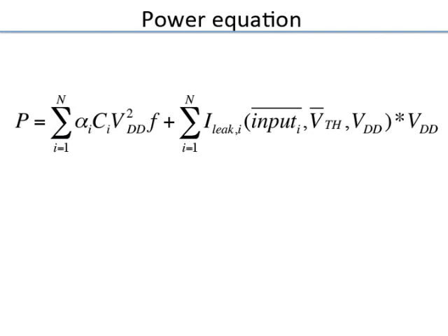If you recall, there is the DIBL effect. The off stack in the CMOS sees a complete VDD voltage across its VDS. That will lead to modulation of the threshold voltage of the transistors, and hence the leakage current, because the subthreshold leakage is exponentially related to the threshold voltage.